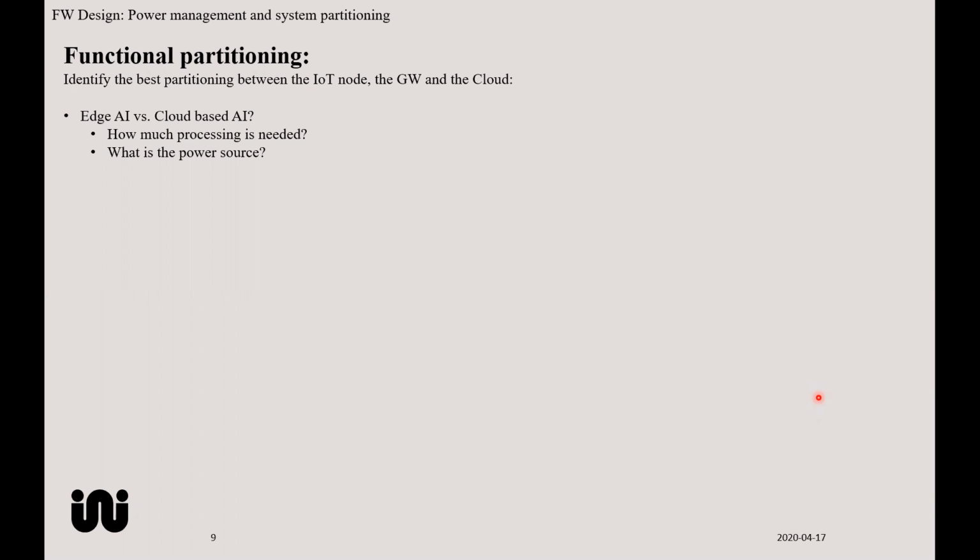If you upload data once an hour so that you can monitor it and do AI processing in the cloud, that will consume power for the connection, with quite many connections over a 24-hour period. If you implement edge AI instead, you sample the sensor and do your processing on the edge, and maybe upload the data once a day.